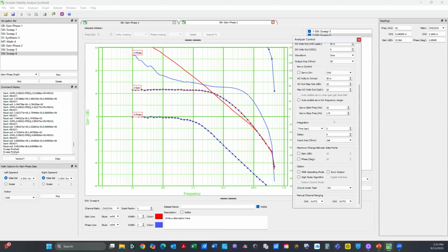If you know anything about discrete Fourier transforms, they're like Fourier transforms, but the longer the time, the narrower the band around that frequency. It's like a notch filter around that frequency that rejects noise. So you get better results at longer times, but the cost is the measurement takes a lot longer to complete.